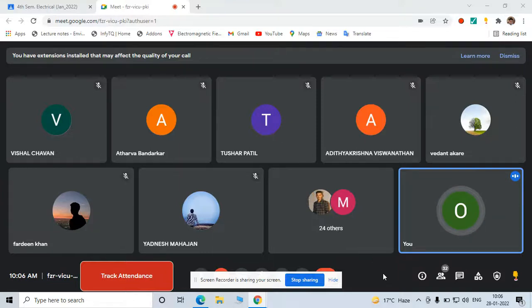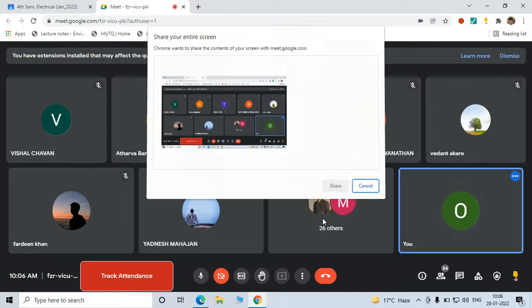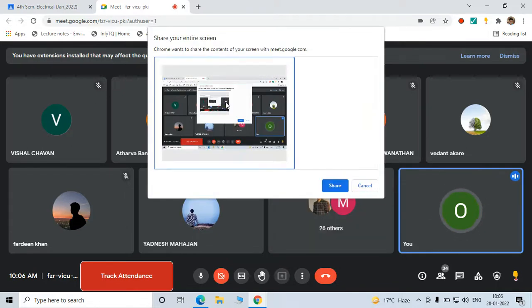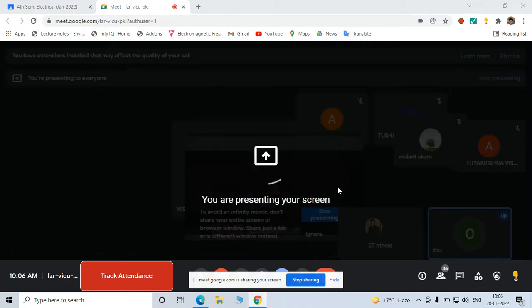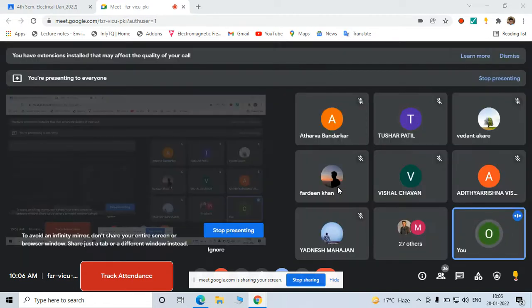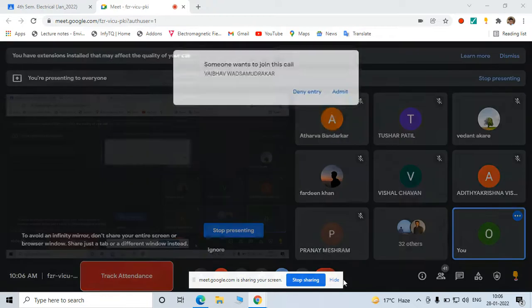See the different types of characteristics which are desirable while selecting any instrument for measuring a reading. For example, the limiting error, which is nothing but the maximum error of any instrument, should be as small as possible. And the other error, for example the percentage guaranteed accuracy error, should also be within a specified range, right? So